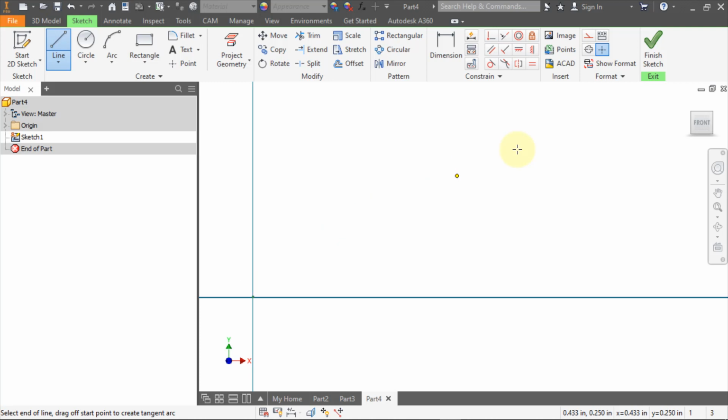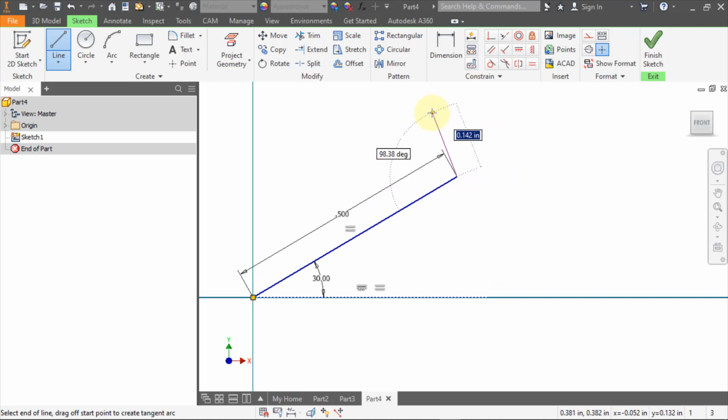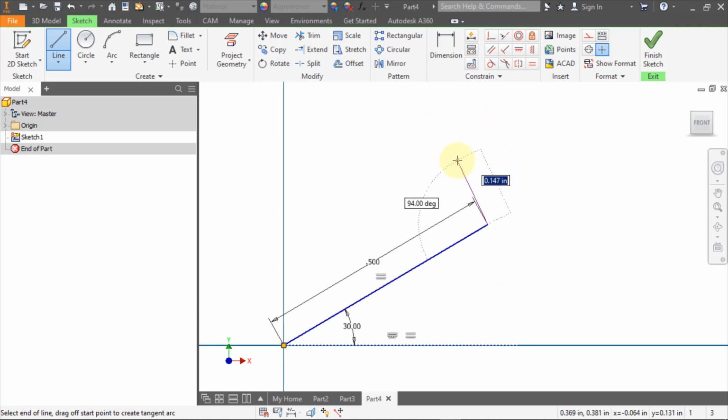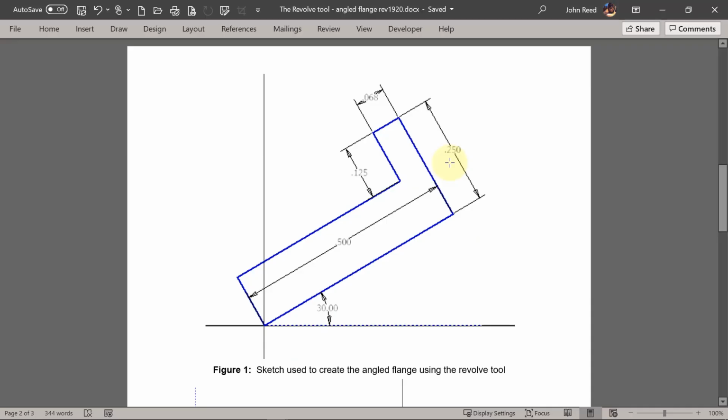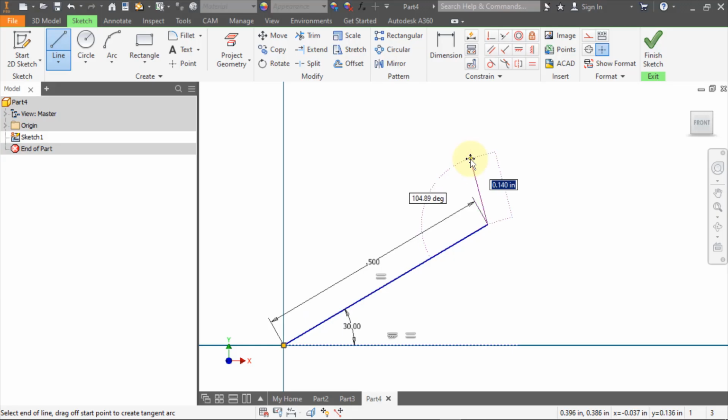So I'm going to left click, and now I want to move over here and make a line perpendicular to that line that is 0.25 inches. And as I move over here, I move until I see the perpendicular glyph, which is behind the 0.152 there, but you can see it. So that distance is going to be 0.25. So I'll tab back over to let it stretch out and get to its right length, and left click, and I'll continue along here.